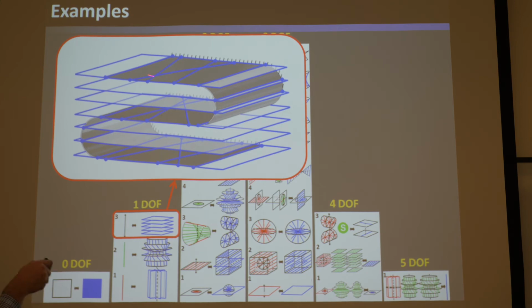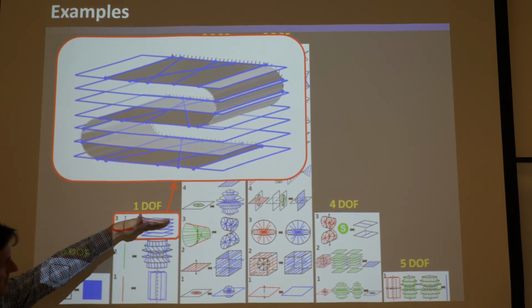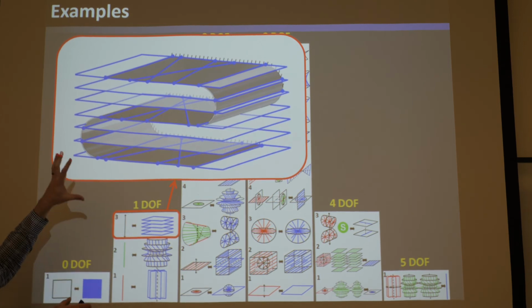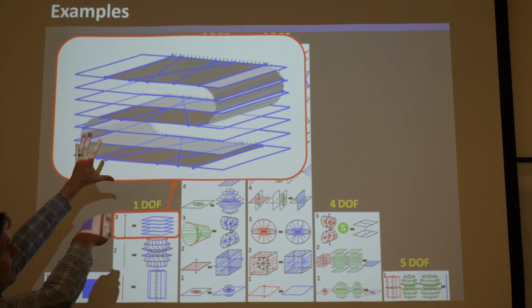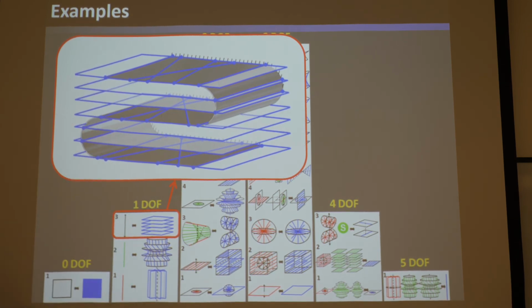But what ends up happening is this entire space lies within parallel stacked planes, an infinite number of parallel stacked planes, and its freedom space is a translation. So if you stuck a ground on this back side and a front stage block on this side, its first mode shape would be a translation. Okay, and then its other mode shapes would be who knows what, and they may actually be associated with natural frequencies that aren't even that much larger. So it's a little gray area here, but according to FACT and ideal constraints, the freedom space of this would be a translation, and it would pretty well correspond with modal analysis as well, as long as you make the stages really large.